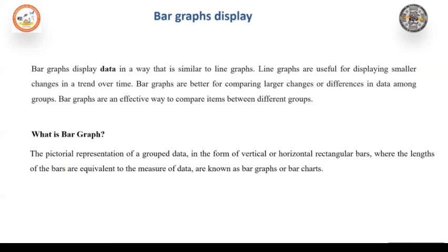The main advantages of such displays are the solid state nature and good response speed. Such displays are generally employed in panel meters to accept analog input signals and give an equivalent display of the input signal level by illuminating the corresponding LEDs.